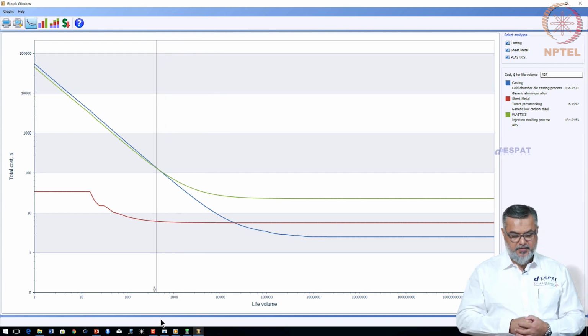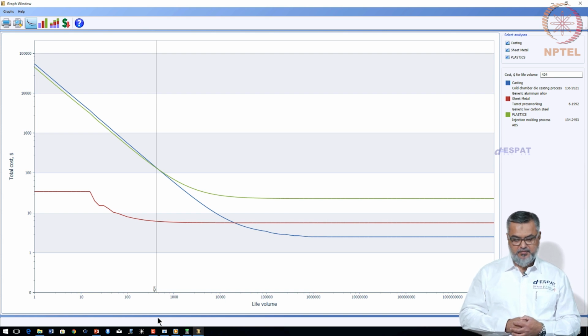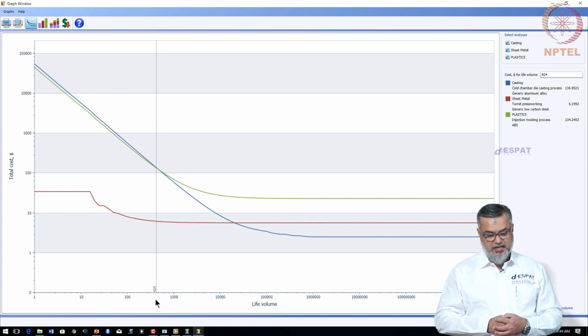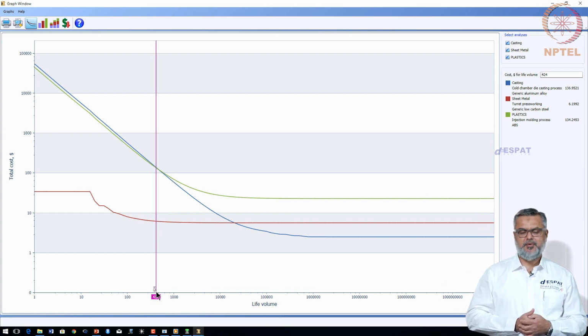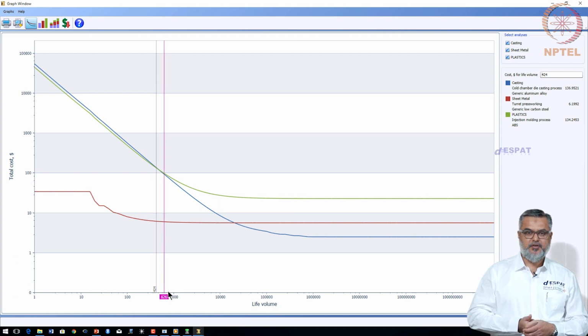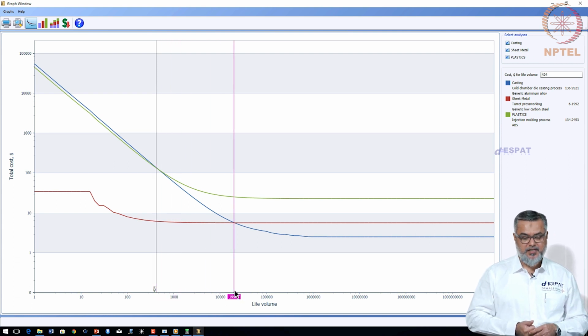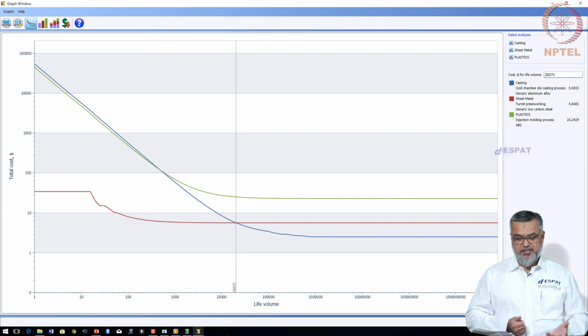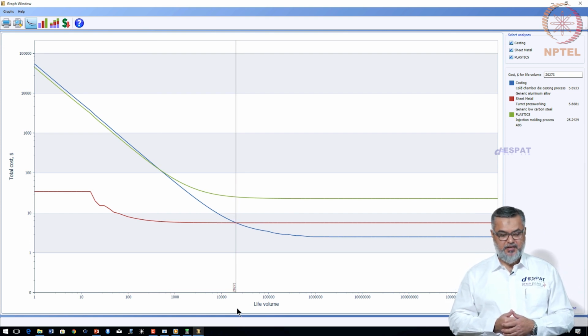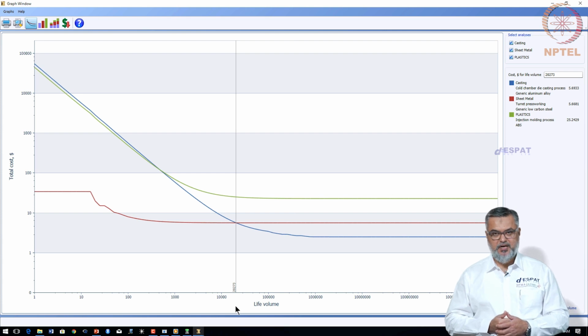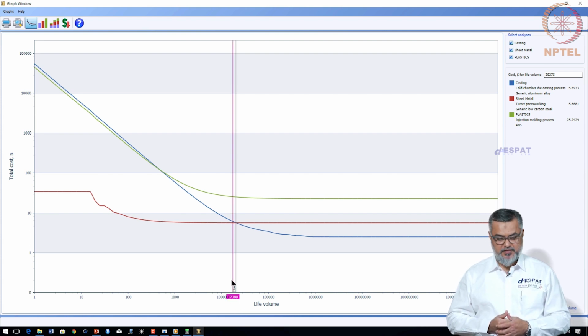you will see that if I want to make 424 plus parts, I can actually match casting at the price of plastic, something somebody would want to investigate if he is not interested to have a plastic part for an automotive design. Or if I move that selection ruler to the intersection of the blue and the red line, I am seeing that if I get a number of about 20,000 plus parts, I can make casting appear much cheaper than sheet metal.